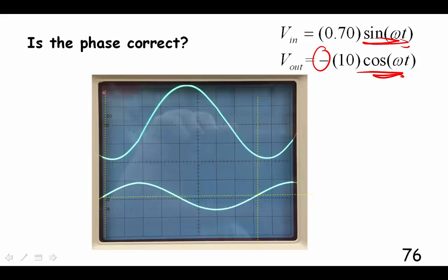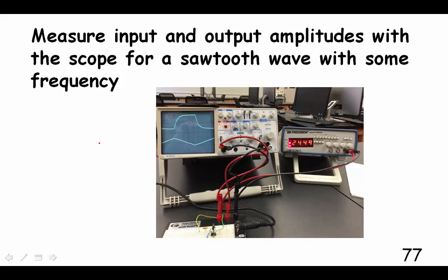If it was a cosine, the cosine would be at its maximum value right there, but if we take a negative sign, it flips it over. So it's almost right, but it's just a little bit late. Why is that? The differentiator is lagging a little bit. Op-amps don't work as well as differentiators as they do as integrators, and we'll see in this particular case it's also quite evident.